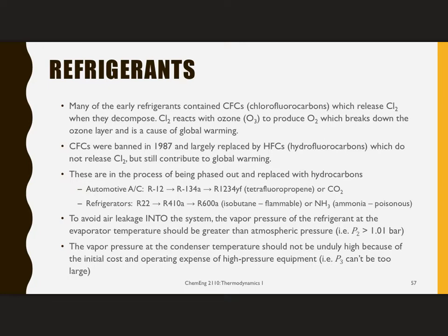Problem is, chlorine reacts with the ozone in the upper atmosphere, which produces oxygen, which ends up breaking down the ozone layer and is an early contributor to global warming. The CFCs were banned in 1987 and largely replaced by hydrofluorocarbons. No more chlorine, but they still had the fluorine there. Now, these HFCs still are greenhouse gases and do contribute to global warming, and so they are in the process of being phased out, and they are being replaced with simpler hydrocarbons where possible.